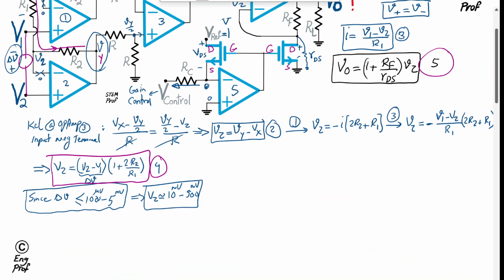Alright, so let's now move on to the design of this segment of the circuit properly and figuring out RDS. One note: these two transistors need to be matched transistors. So they should be in the same package, and that would guarantee they're on the same substrate and benefit from the same junction properties, so that this would mimic the behavior of this transistor.